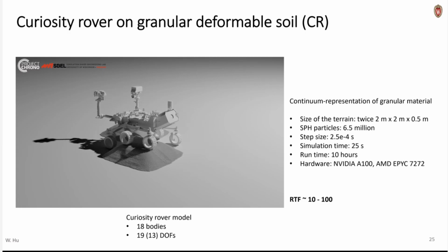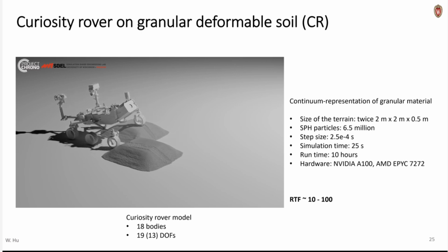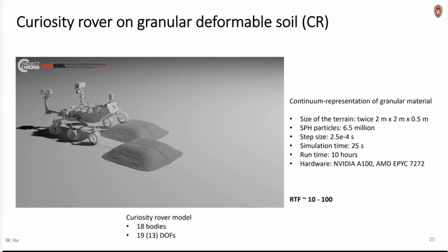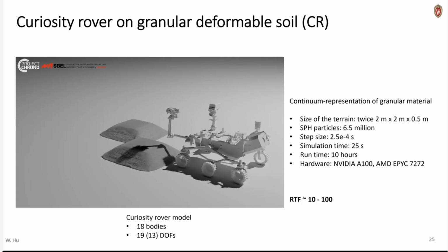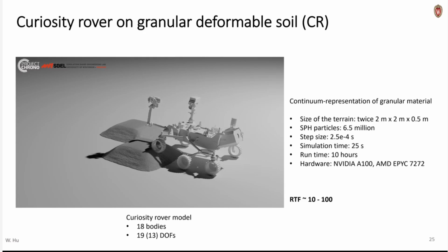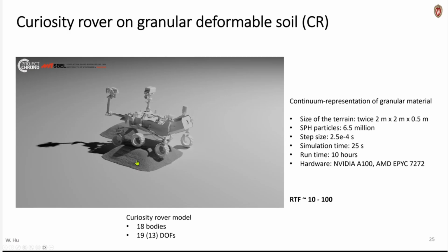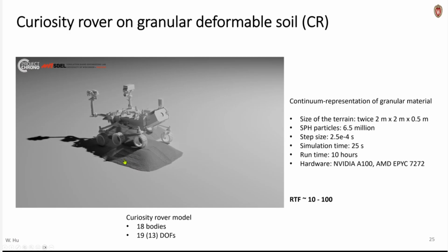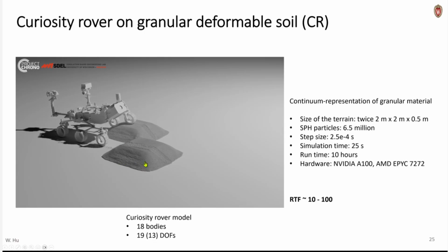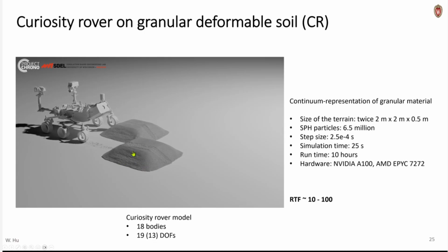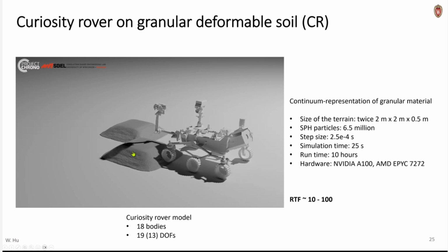This is, if you want, like a homogenization of the granular dynamics equations, and solving an equivalent set of PDEs. So moving to the continuum representation, a set of PDEs that we solve the same way as we do fluid-solid interaction. So at this point, whether this is water and this phase is modeled with the Navier-Stokes PDEs, or if we decide it's soil and it's modeled with these continuous PDEs that model soil, is the same thing. We have the machinery to solve these kind of problems.